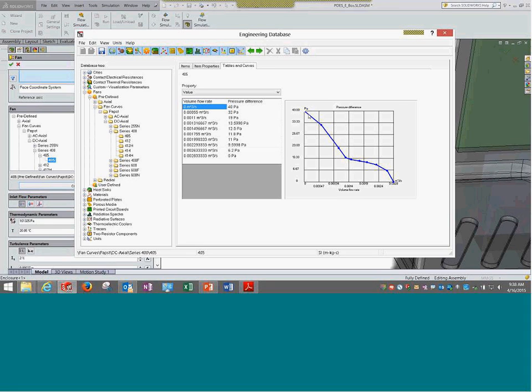I'm not sure if I'm able to convey this point correctly, but at a particular amount of pressure, the flow rate is said to be optimal, where the efficiency of the fan is maximum. In the graph we are seeing only one curve. Typically there will be more curves which show similar characteristics for the system, not for the fan but for the system.